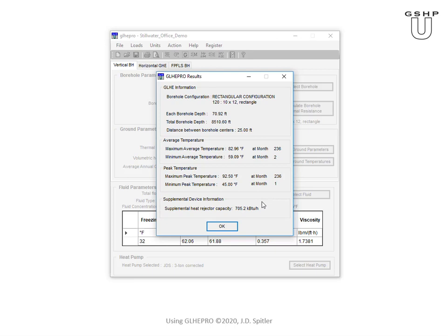I only brought this up because we have 7.4 times the cooling load, 7.4 times the total heating load for the year. When we do a hybrid system, what we're really trying to do, in our case, is not absolutely balance the loads, but hit both the cooling and heating design temperatures.